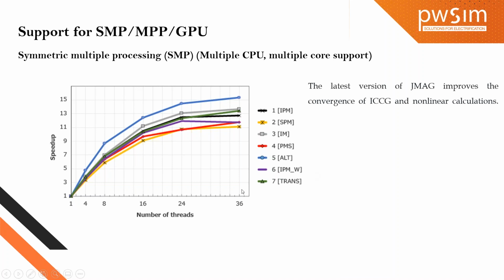For a given SMP, that is shared memory processing, it can use up to 36 cores. 36 cores means we define it in PA2, parallel accelerator. Each PA2 will have 2 cores. So to reach the complete 36 cores, we need 18 PA2s.